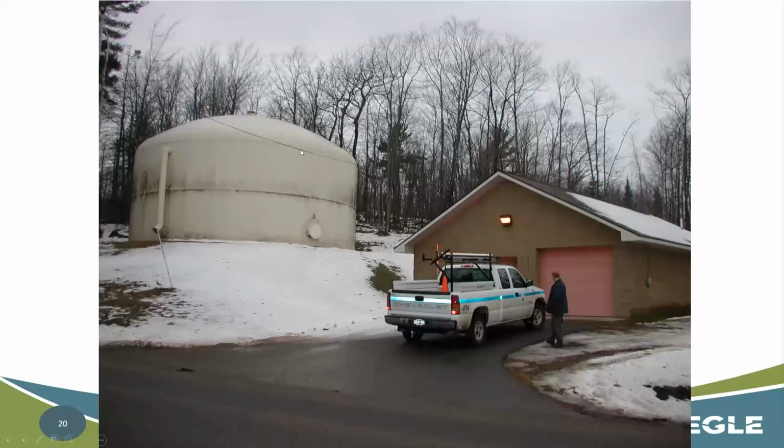So here's another example of just a ground storage tank. Again, according to the speaker notes, I'm not aware of this specific instance, but this is actually considered somewhat of an elevated tank. So this is uphill. You have your well house here. This is uphill of whatever the community is. So that's actually maintaining pressure to the system because it's on a higher elevation, basically.